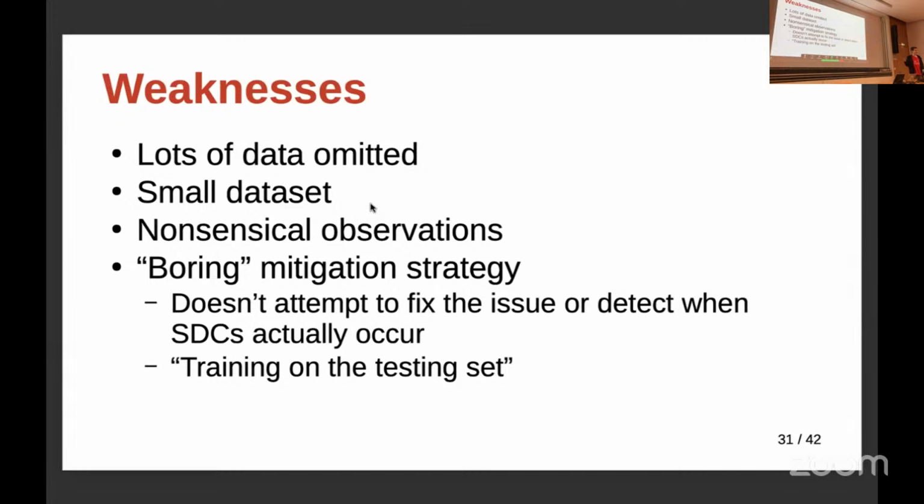It's also problematic because they're training on their testing data set, in that by focusing only on test cases which have already found faults, sure, they're increasing the likelihood that they'll pick up other faults of that type, but we don't know if maybe in the future, as the silicon degrades, there might be a new kind of fault that can only be detected by one of the test cases that got deprioritized. So their system is biasing them towards their own observation that only some test cases actually find faults. If a new test case started to find things in the future, it wouldn't be picked up.